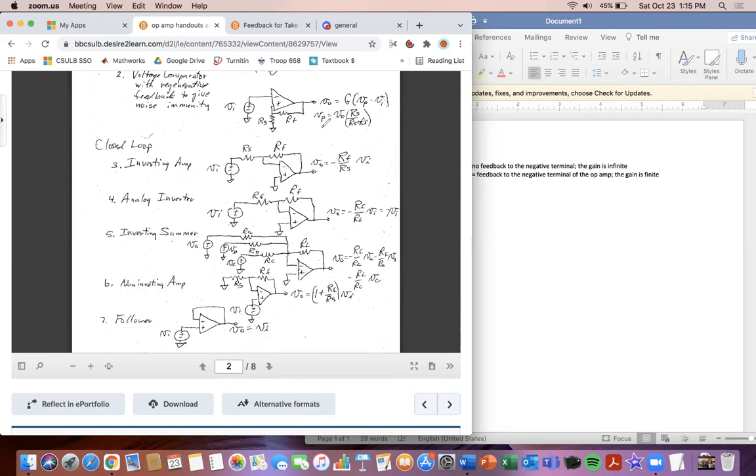And so you guys know how these equations come into being. You can do the derivation of them where you actually do Kirchhoff's current law. So I'll show that for one of them, but after that, you can basically apply it to the rest. But I want to tell you guys how I memorize these. So for the inverting amp, I know it's the gain, and then we know from our equation, it's usually the gain times VP minus VN. And we know our gain here.